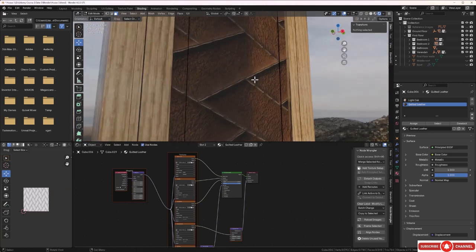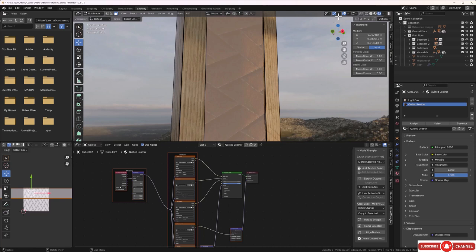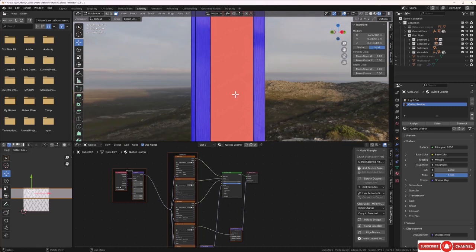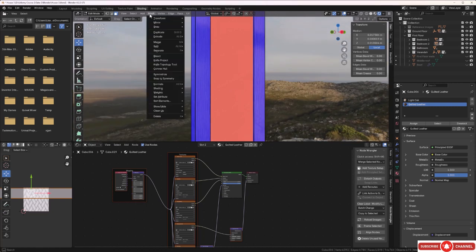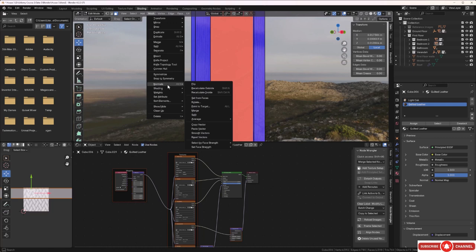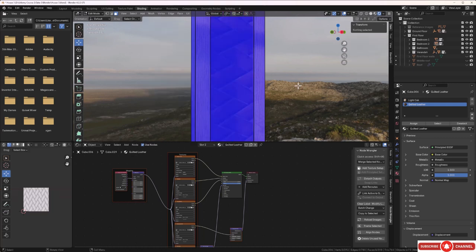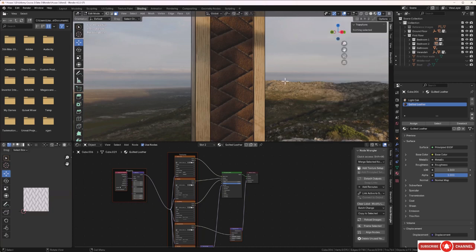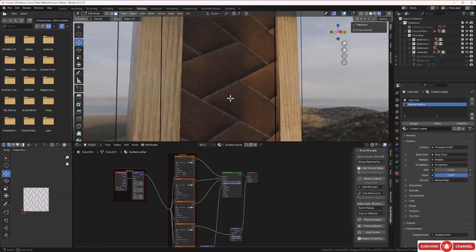And I just want to check the normal maps on this. I'll select this object and I'll come over to this one and face orientation, and it looked like the normal was out. I was right. So I'll select this item here. I'll go to mesh, go to normals and flip this one, and there we go. We'll turn the face orientation back off again, and that's looking better.